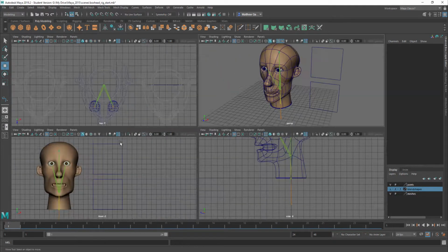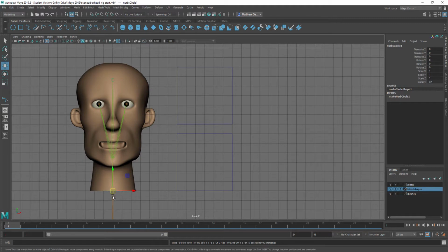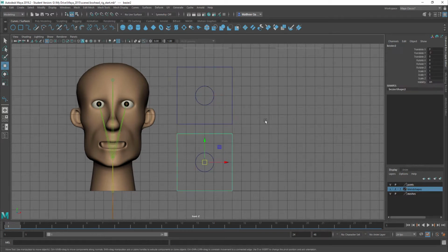They're both like that. Then I'm going to create a little circle for each of these, which is going to be the actual controller. We can use a circle, and it's flat to the floor, so I just need to rotate it 90 degrees on the X. Just type in 90, and I'm then going to move that. I'm grid snapping it again, holding X down, and I want that dead center in that square. And I'll make a duplicate, Control D, and again grid snap that one dead center in that square.